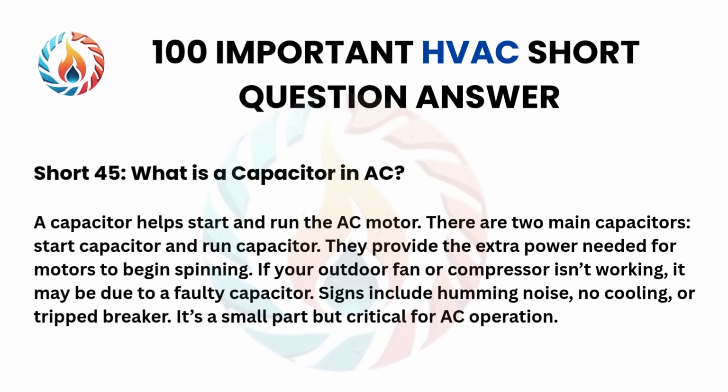Short 45. What is a capacitor in AC? A capacitor helps start and run the AC motor. There are two main capacitors: start capacitor and run capacitor. They provide the extra power needed for motors to begin spinning. If your outdoor fan or compressor isn't working, it may be due to a faulty capacitor. Signs include humming noise, no cooling, or tripped breaker. It's a small part but critical for AC operation.